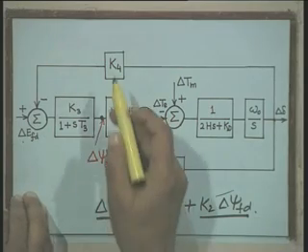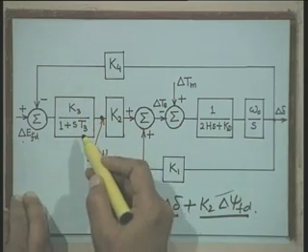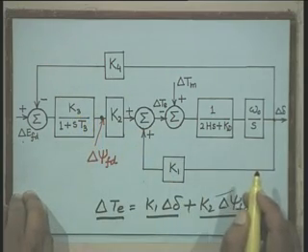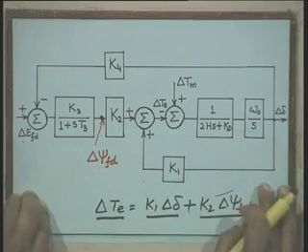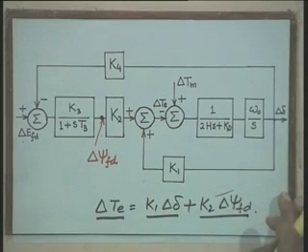Now, this K 4, K 3 and T 3 are again constants, and they depend upon the system operating condition and parameters. Therefore, this is the model which accounts for the synchronous machine field winding dynamics.